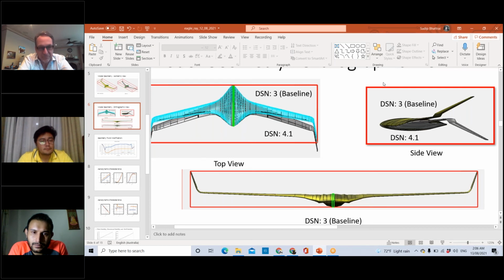Say if I want to trim to a speed very close to stall speed, even if I was able to trim it, for some reason it chooses to just go for a condition where it keeps losing speed very, very slowly. So most of the stall that I noticed was not because it would keep pitching up, but for some reason it just kept losing speed.